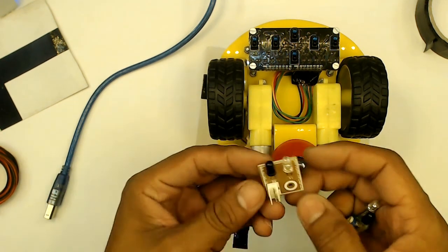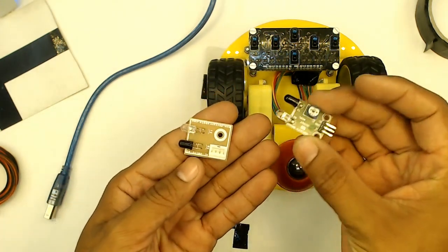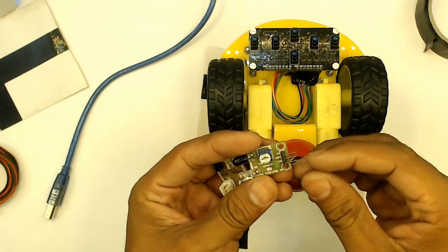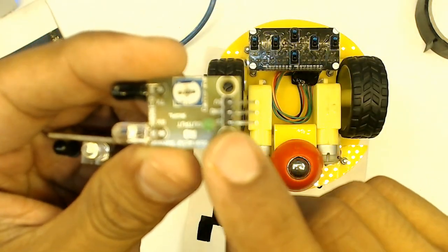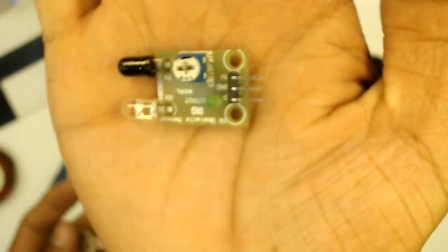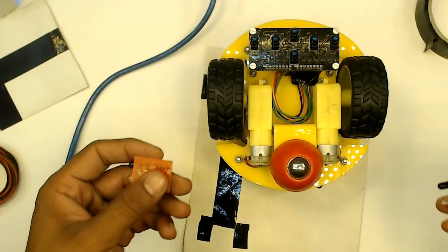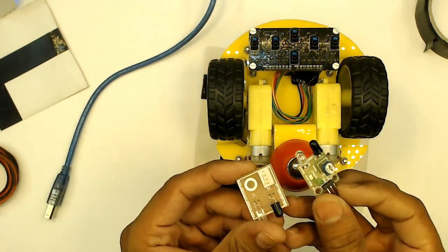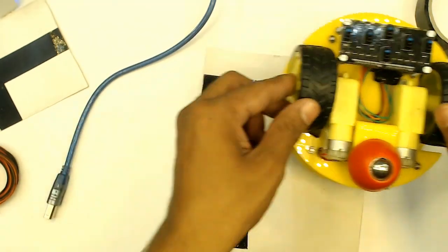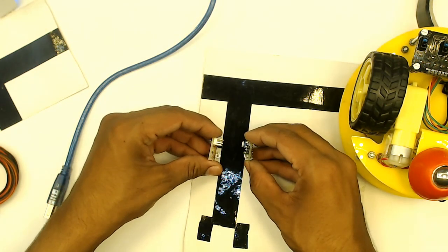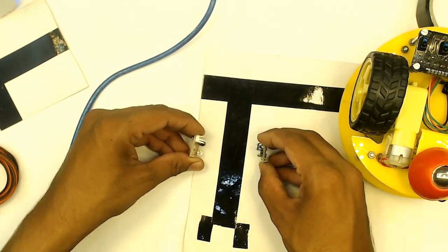So you can prefer having sensors like this or like this. The only disadvantage that I told you about this one is you need to apply separate VCC and ground to each of this particular IC. Whereas if you're using a common combo IR line sensor array, then things become pretty much simple. But the advantage that you gain by using these discrete IR sensors is that depending upon the width of your track, you can adjust them to be very near or very far away.